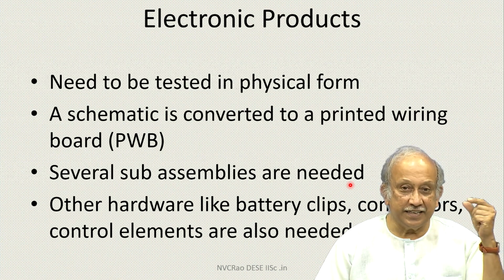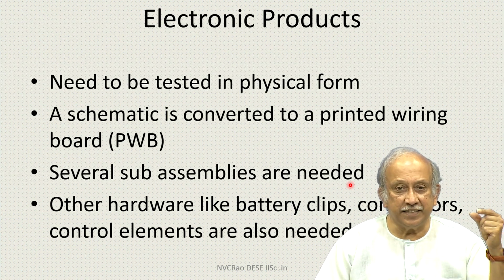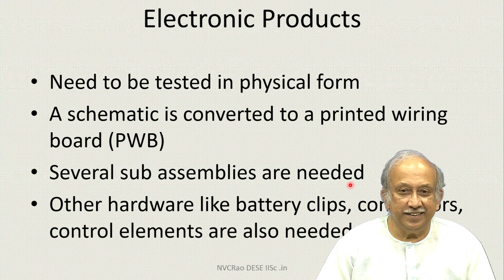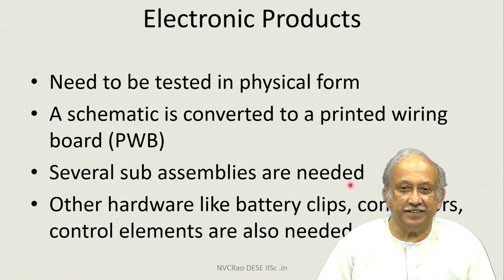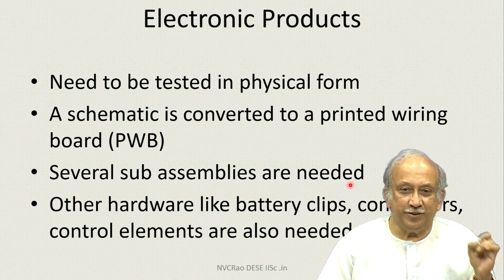However, if you take the connector which is called micro USB or type C or anything, the connector itself is capable of taking a shocking amount of power. Several of them are very much capable of taking 10 amps at 5 volts, 50 watts, but for an extremely short duration.